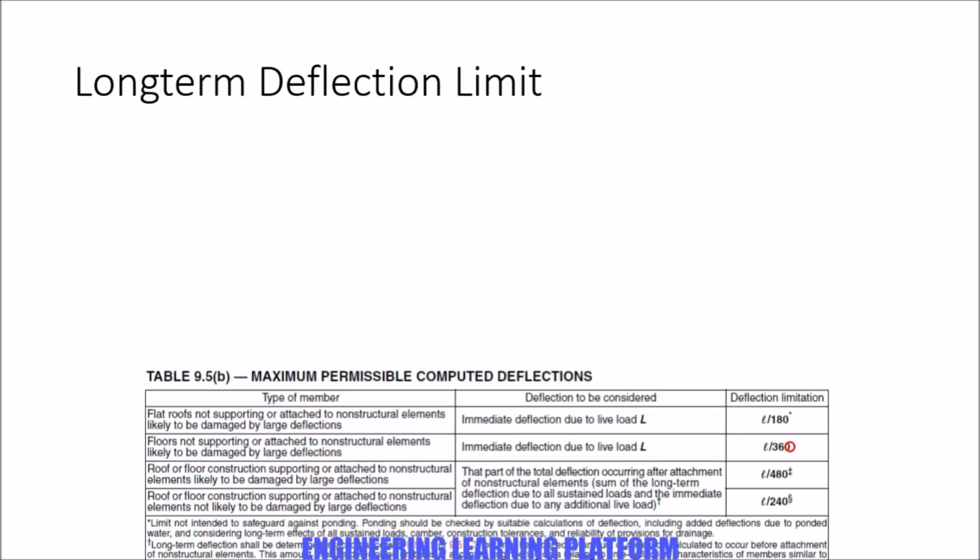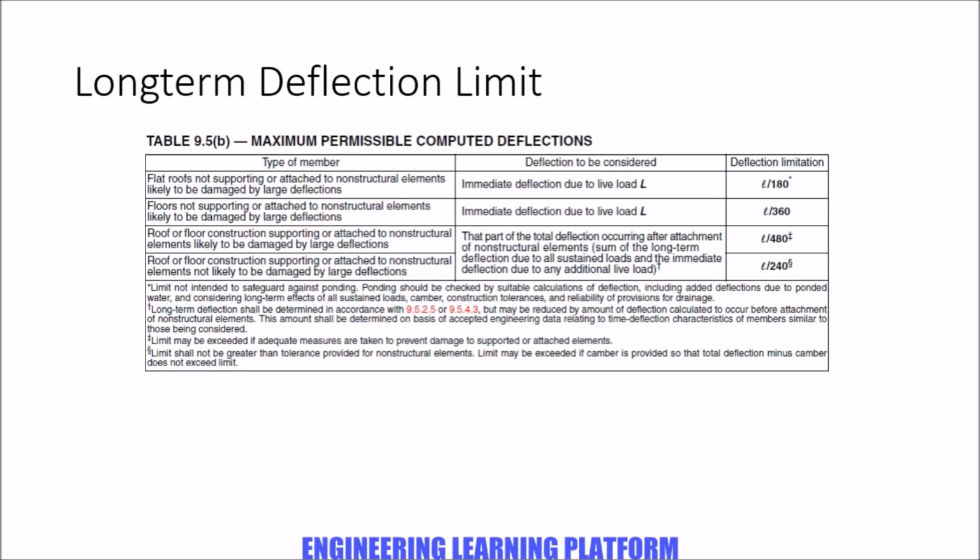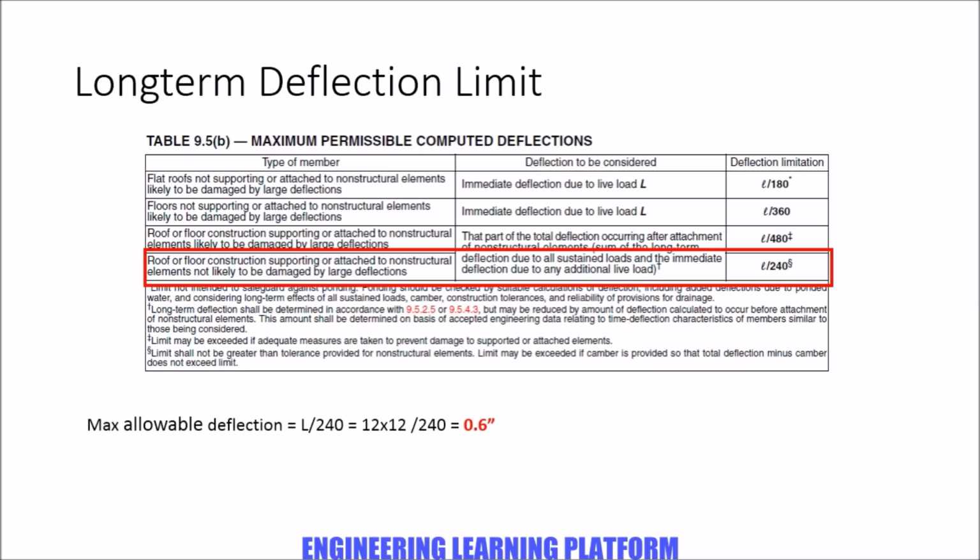The long-term deflection limit for flat plate and flat slabs is L by 240, where L is 12 feet in our case. So the deflection limit is 0.6 inches.